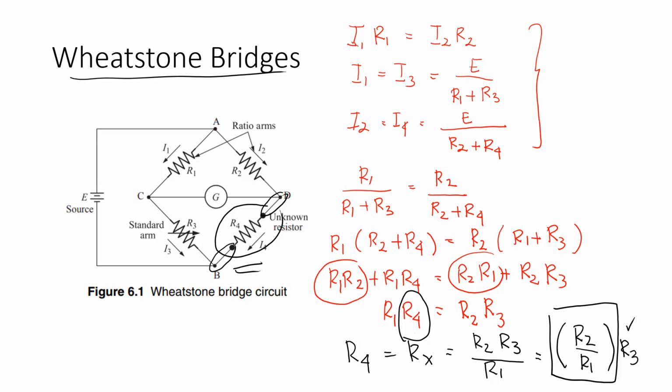If we connect resistors, sometimes we can get thermal energy. The thermal energy in the circuit will affect the balancing of the bridge. If the balancing of the bridge is affected by the thermal electromotive force, the Wheatstone bridge is not ideal, so we cannot use it to measure the unknown resistor.